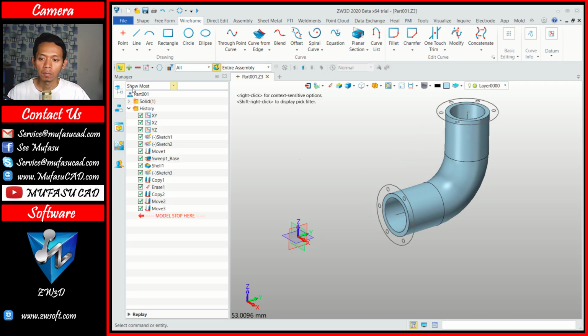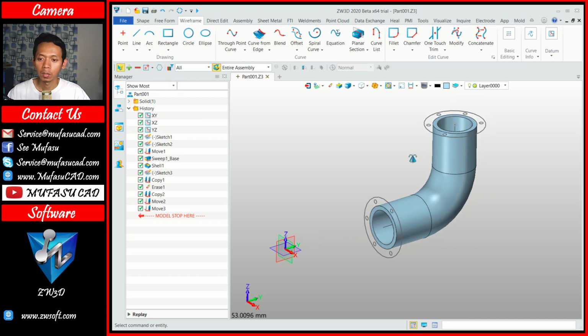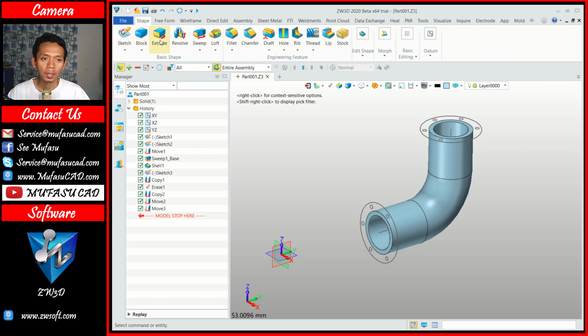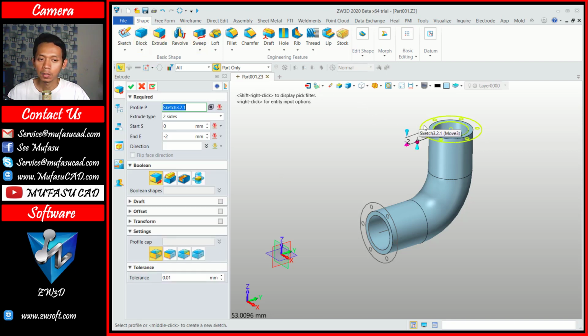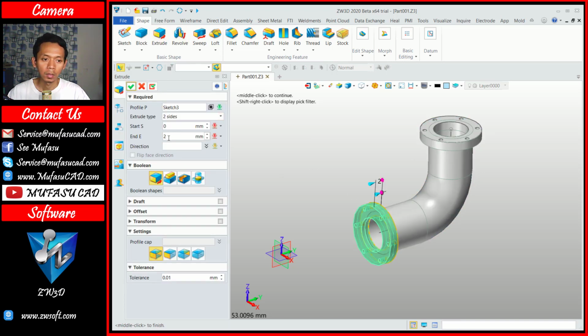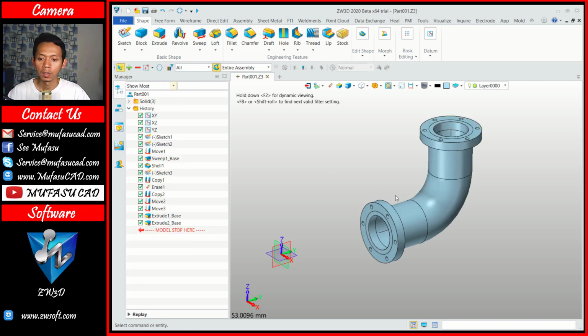Finally, we can convert these sketches into 3D models by using the extrude command. You can click solid and then click extrude. We can select this profile. We extrude in here by 2 and you can click OK. We extrude this object again with an extrusion of -2 and you can click OK to apply.